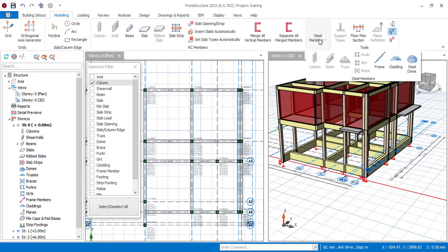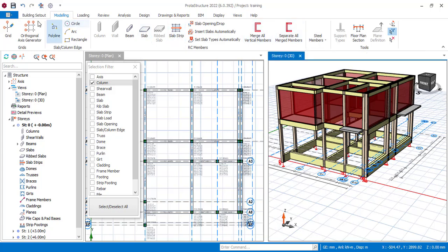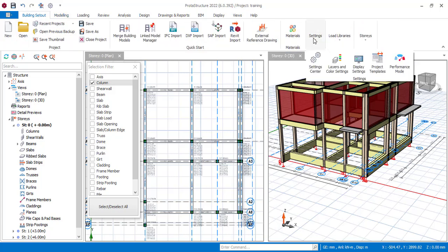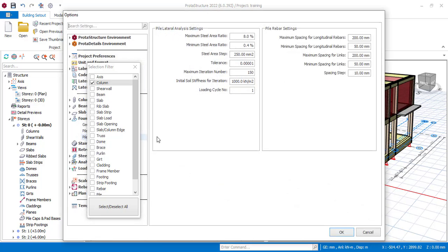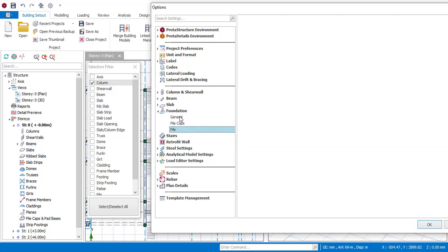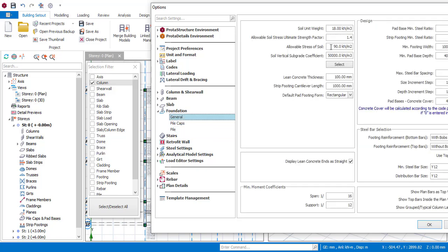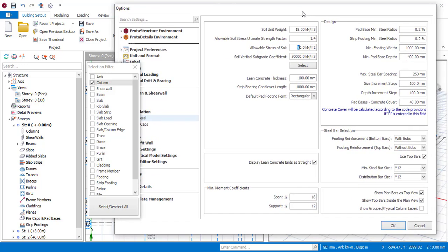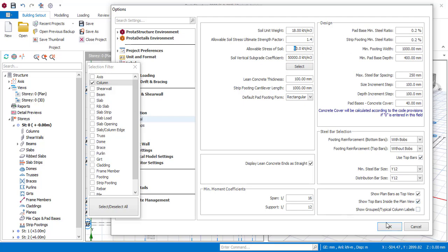Okay, so if everything is done right and the soil bearing capacity is wrong, you will definitely be having a very wrong result. So what we got there from the soil report is 90 kilonewton per meter square, based on what the soil engineer has specified as the geotechnical engineer.